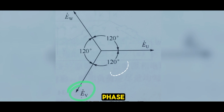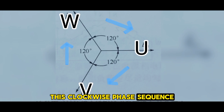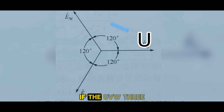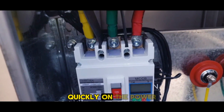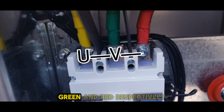is the lagging phase. In the diagram, we see that the angles of the UVW three phases each add up to 120 degrees, and the three phases are arranged in a clockwise manner. This clockwise phase sequence arrangement is called the positive phase sequence, or simply positive sequence. If the UVW three phases are arranged in a counterclockwise sequence, it is called the reverse phase sequence, or simply reverse sequence. Typically, on the power bus, the three phases UVW are represented by the colors yellow, green, and red,